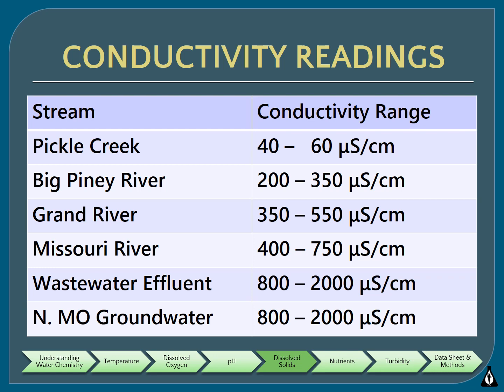In general, the larger the water body, the larger the surface area of the watershed, and therefore the greater the point and non-point source impacts that could potentially be influencing the conductivity of the stream. For example, the Missouri River is a very large watershed. A lot of point sources and non-point sources are coming into this stream. Therefore, the conductivity readings and ranges are going to be higher simply because of the size of the watershed.